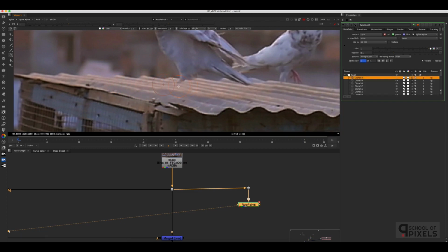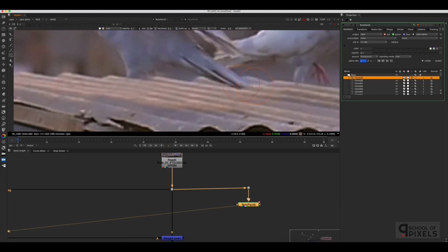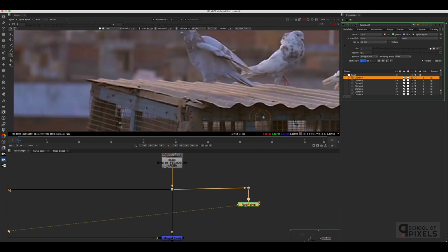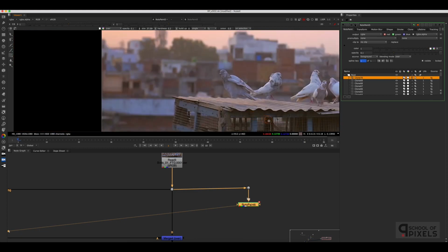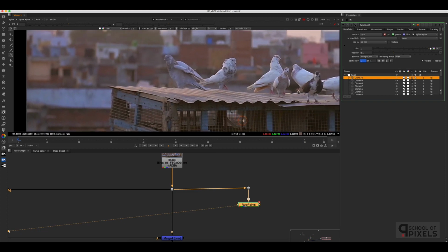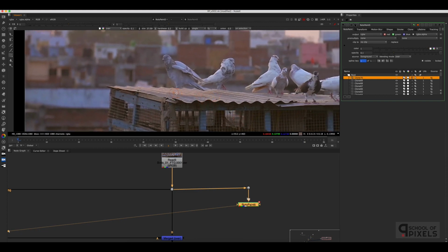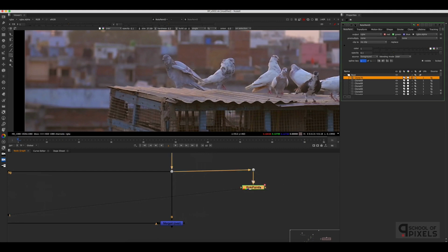So you can see I have to line up those edges to make sure I'm painting correctly. So you can spend a bit more time on painting this, because once you have a proper paint out done, it's much easier than going back and fixing it again and again. So you can take some time, make sure all your edges are working properly and this looks nice and consistent. And once you've done the paint out, there's two options: to keep the frame or paint out at every frame.